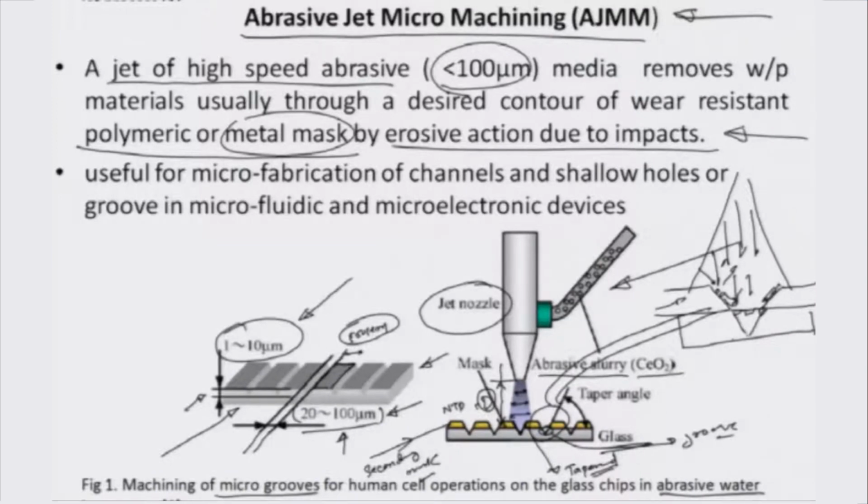That is the reason for the tapering: some particles which are deflected off the surface of the mask go rolling along this tapered mask and hit the surface at a high impact, creating the brittle fracture also in a tapered manner. So one of the reasons, as Matsumura observed here, is how beautifully the grooves and shapes can be defined by just positioning and structuring.